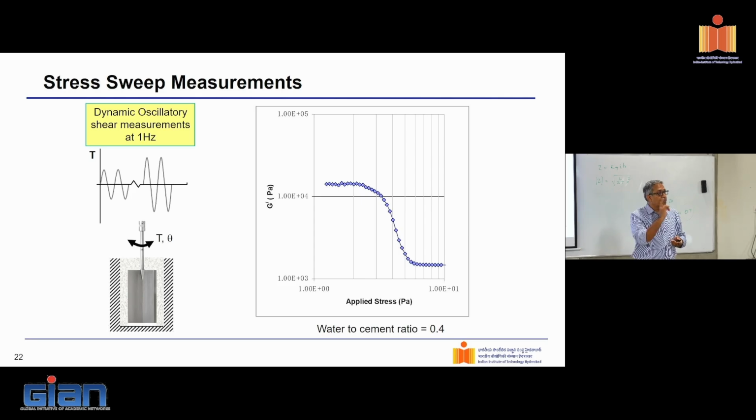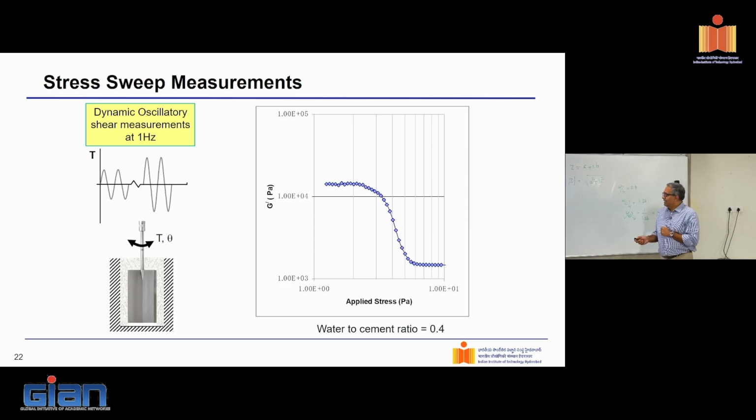I'm measuring the shear modulus of the skeleton that is present inside. The shear resistance that I'm getting from the skeleton inside is constant. If I increase the amplitude, at some point, it'll just shear off. And so this is another measure that we use for our yield stress, as was described before. And for such a measurement, in fact, the vane tool is probably the best tool to determine the yield stress.